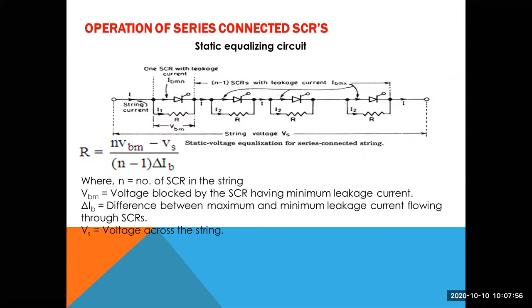To eliminate this drawback, remember the selection of the R value. Because current is already flowing in the string when the switch is off, the resistance should be more. If you take a larger resistance value, the additional current will be reduced. When the SCR is off, current flows through the resistance.